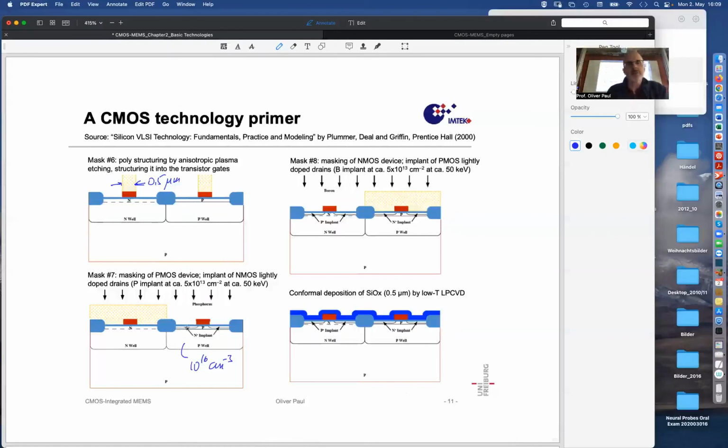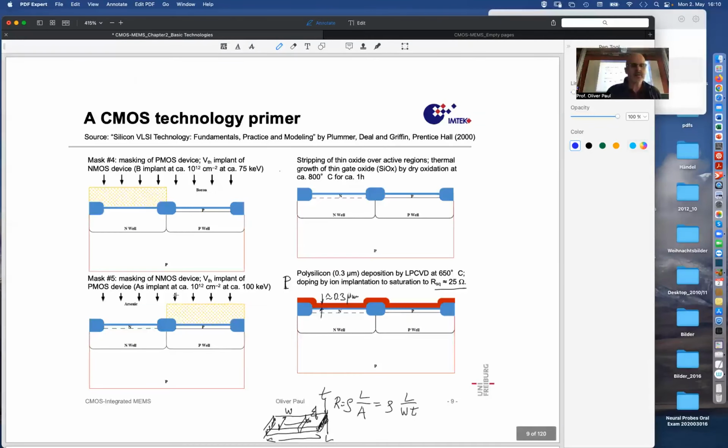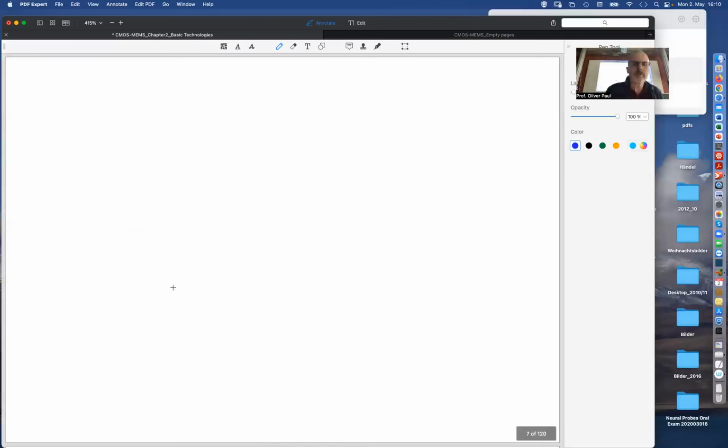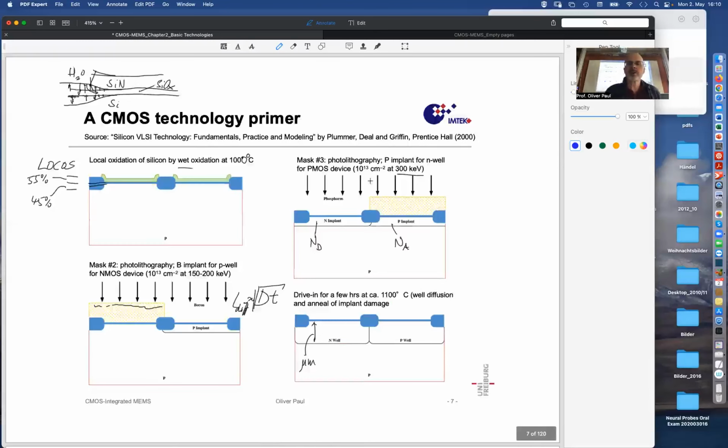And then during the subsequent thermal history, those dopants get built into the crystal, and they get redistributed a little bit, but not very far, because the temperatures don't reach these high temperatures anymore as we had before. In order to redistribute the dopants that created the well, that were implanted at 10 to the 12, no, what was it? Here, much more, 10 to the 13 at really high voltages. We needed then anneals at 1,100 degrees.